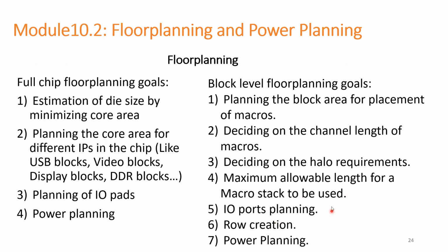IO ports planning. Sometimes the top level engineer will ask the block level engineer to decide the IO port location. So the block level engineer has to place the IOs, decide wherever there is a good location for the ports, and give the details to the top level engineer. Accordingly, he will align with the block level IOs.